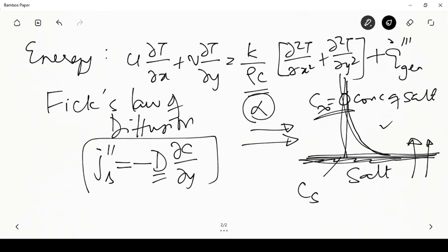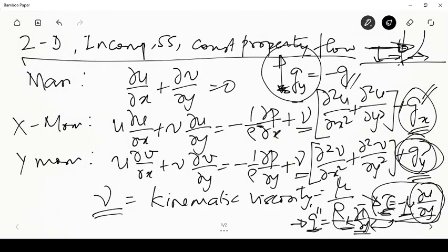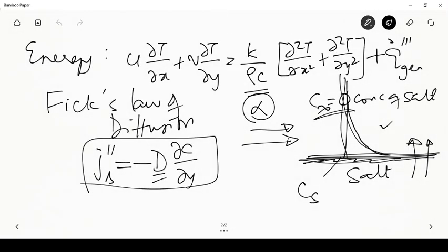So this also has a very similar form to the previous two expressions that we saw. The shear stress, which is proportional to the velocity gradient, the heat flux, which is proportional to the temperature gradient, and here you have the mass flux, which is proportional to the concentration gradient. And applying this in deriving the equation of transport, we will get the species equation, which is the conservation of mass of individual species, written in terms of the concentration, which is nothing but the number of moles of a particular species per cubic meter of the solution.